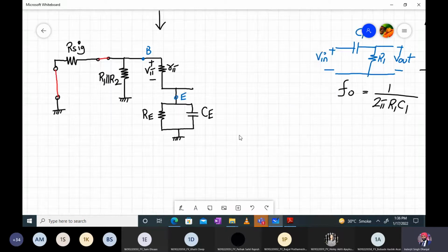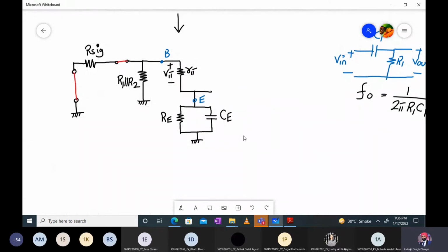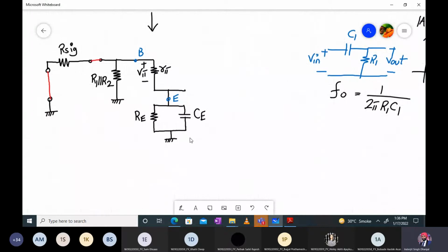Related to that, now listen very carefully. Now can I say that over here R equivalent will be this much. This will be my R equivalent. Let me mark it over here with a red color. R equivalent will be this much, looking into the emitter terminal. Looking into the emitter terminal will be with this only. It will include RE also, so this entire resistance will come.